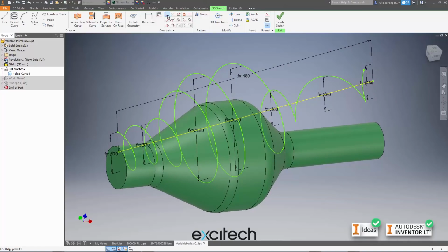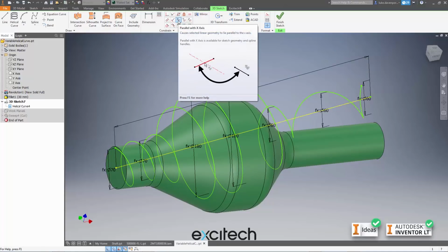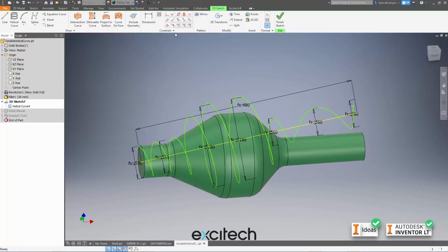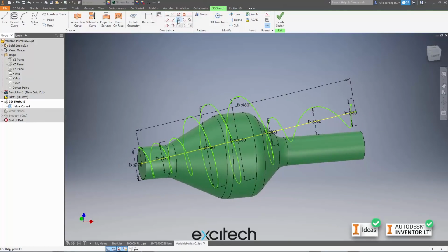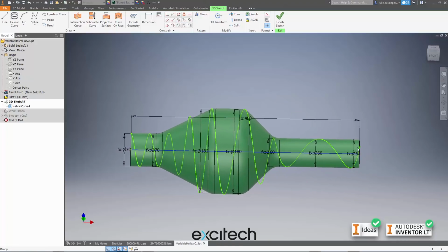So I would do things like put a coincident constraint between there and the origin of my part, which sorts that one out, and then I would probably put a parallel constraint. Which axis do I want it to be aligned with? Is that the x-axis? I'll say I want this line to be parallel with the x-axis. Yep, and now it can't be moved.